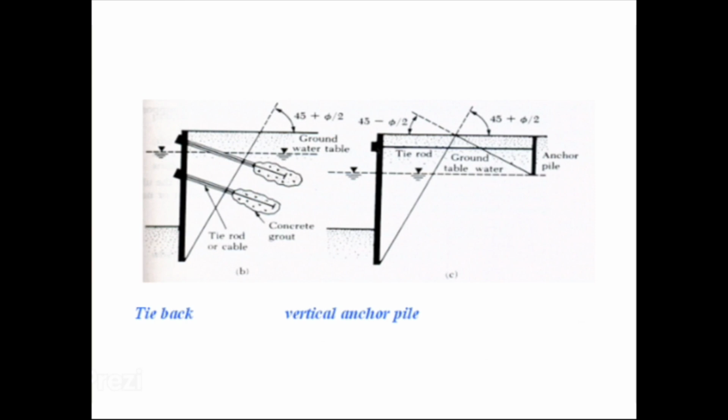Then, we have the vertical anchor pile. But what is an anchor pile? Anchor piles are required to resist lateral loads, with or without being braced depending on circumstances, and an ordinary or standard house pile is required to carry a vertical load. The lateral load capacity of timber pile foundation systems is set out in NZS 3604, which covers timber frame buildings for structural design on good ground.